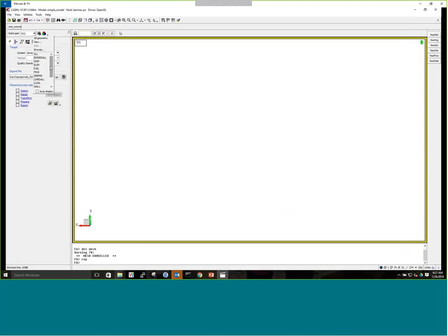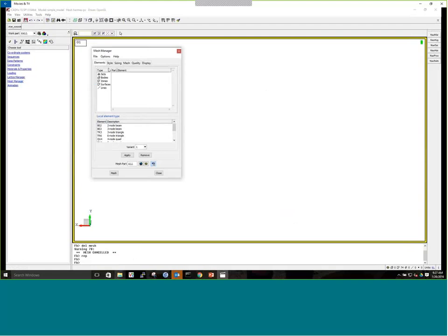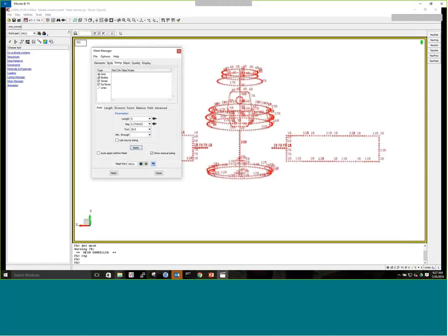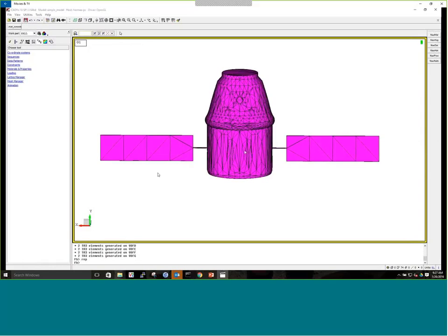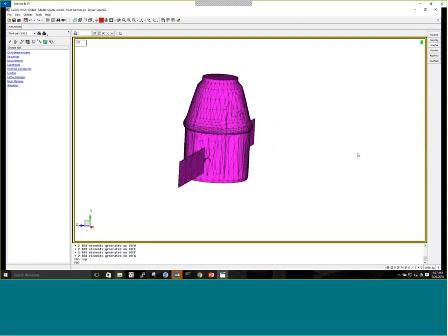So I delete the mesh here, and I select the set we've been working with. SALL has all the surfaces. And I go into this mesh manager, and I'm going to change the mesh algorithm to a curvature sensitive meshing. And I can change the resolution. I picked 5 here just because it ended up looking the most natural to me. And I remesh and repaint it, and boom, here we have the same object, same geometry with the materials, but we have a different mesh.